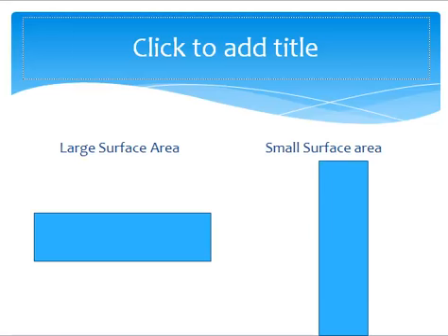It is also important to note that a tank with a large surface area is more effective than a tank with a smaller surface area when the volumes are equal. The larger surface area results in a smaller overflow rate. Therefore, a shallow tank with a larger surface area is more desirable than a deep tank with the same volume.